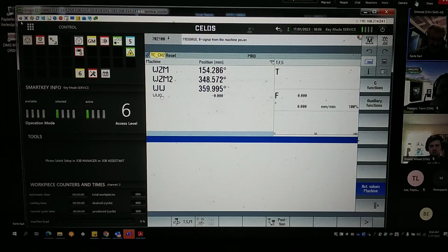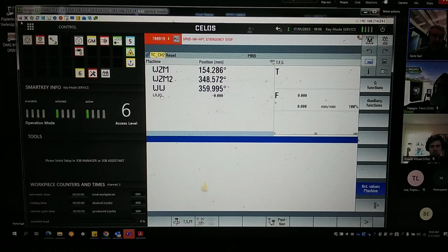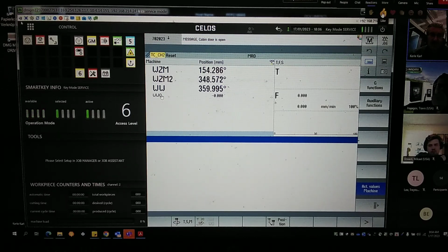So far so good. And now again, 31 axes maximum, but here, let's say it must be a minimum of 6 axes, a spindle, then we can have a certain number of auxiliary axes, and then also a certain number of main axes, for example, with 2 measuring devices. And the total number of 31 axes could never be controlled in one channel.